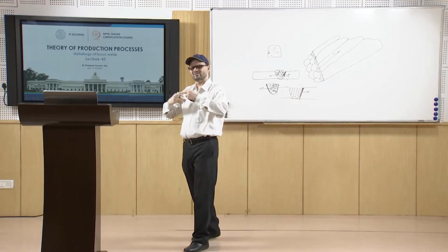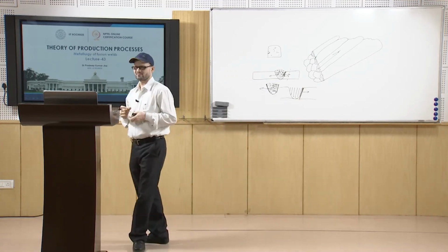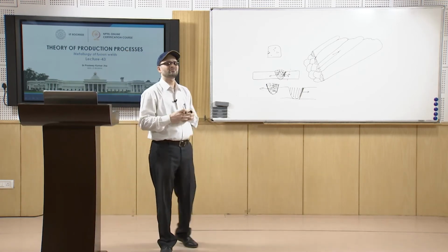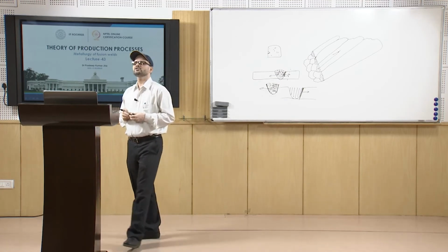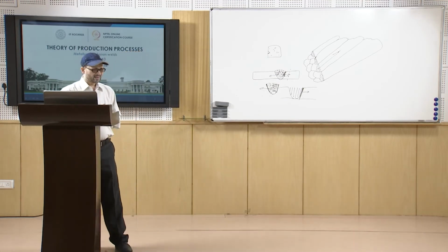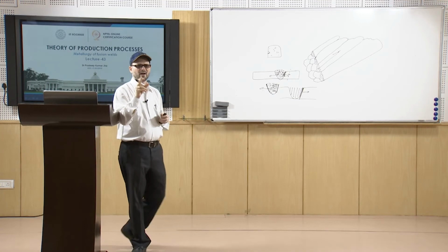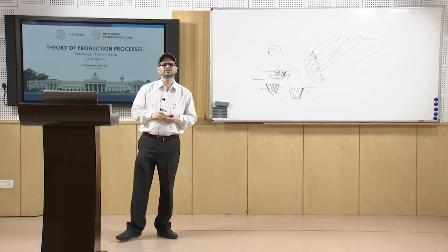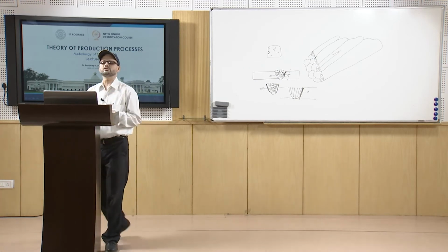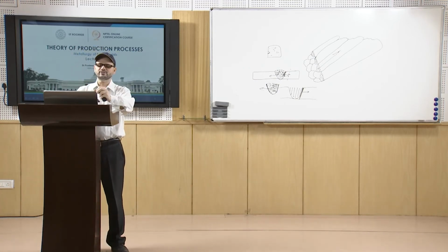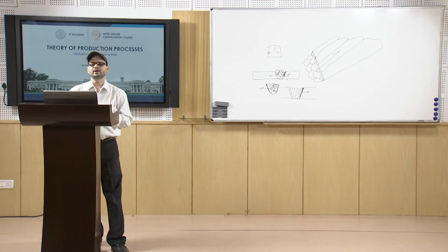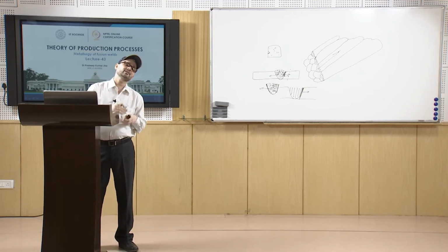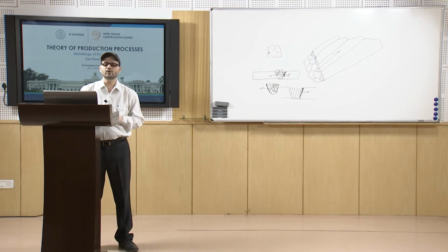Now, when you have alloys with a larger freezing range, in those cases there may be partial melting that takes place in the HAZ, which is adjacent to the weld deposit. That is basically a problem in the case of these higher freezing range alloys.